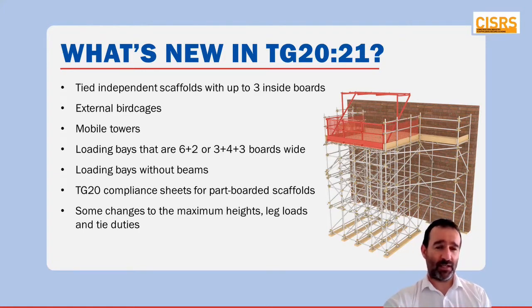This is mostly to enable scaffold designers and temporary works engineers to be able to check the results by hand using the information in the design guide. Whereas in TG 2013, some of these values could only be replicated with an advanced structural analysis.